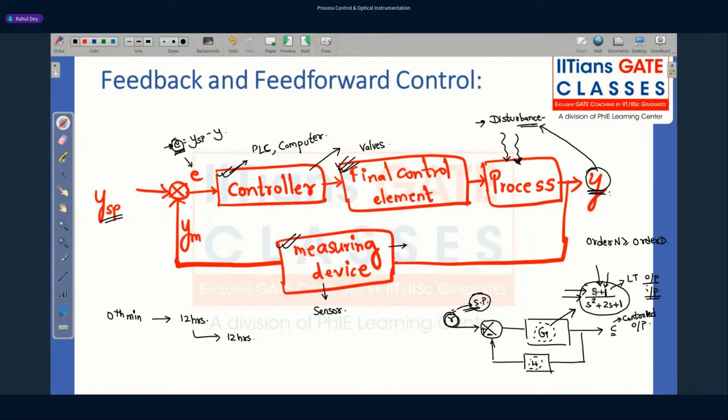Theoretically, whatever the impulse response is, if we take the Laplace transform of it, we will get the transfer function. That is a theoretical thing, but practically it is very, very difficult to obtain the transfer function like that. Can anyone tell me why it is difficult? Because an ideal impulse signal is not possible to generate. So that is why calculating the transfer function is also very, very difficult. Fine.